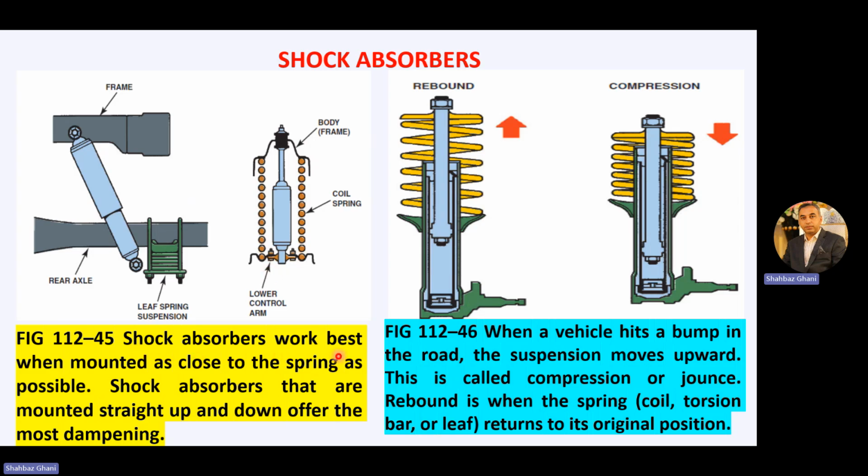The shock absorber works best when mounted as close to the spring as possible. So in the normal McPherson strut, the coil spring surrounds the shock absorber, so they are in one assembly.